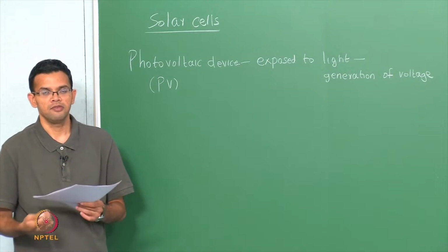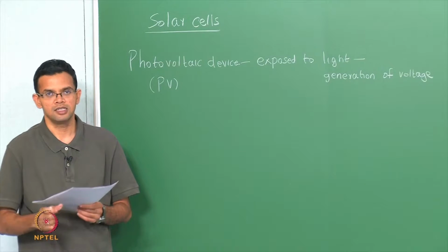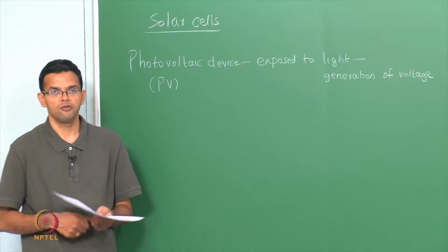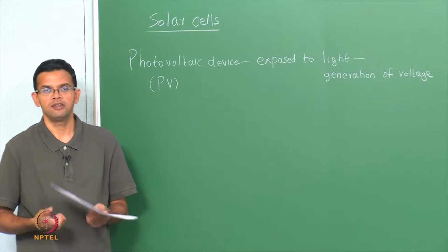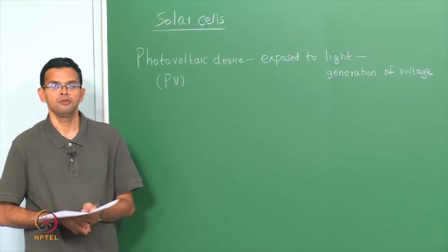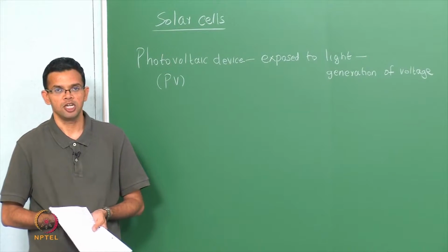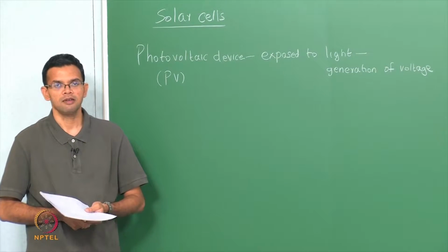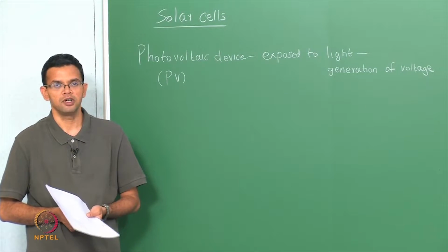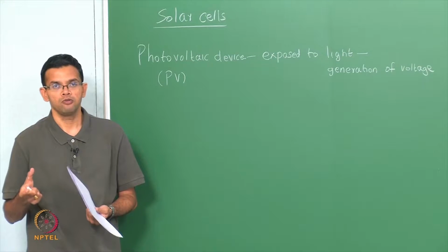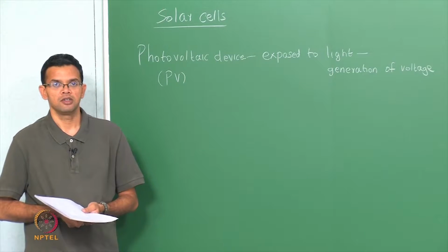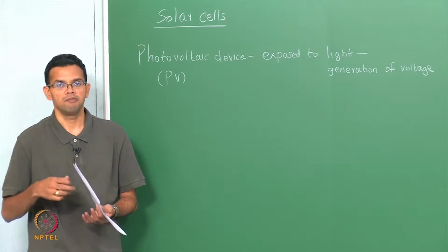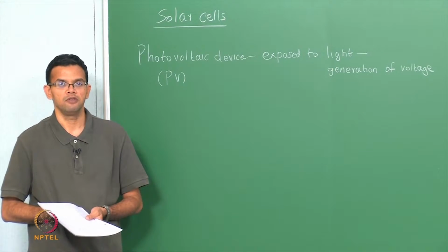photodetector that we looked at last class. There are just a few crucial differences. So in the case of a photodetector, we saw that one such example was a photodiode. It could be a simple p-n junction or a pin junction. So in that case, a photodetector works over a narrow wavelength range. So the maximum wavelength depended upon the energy of the transition that was involved.